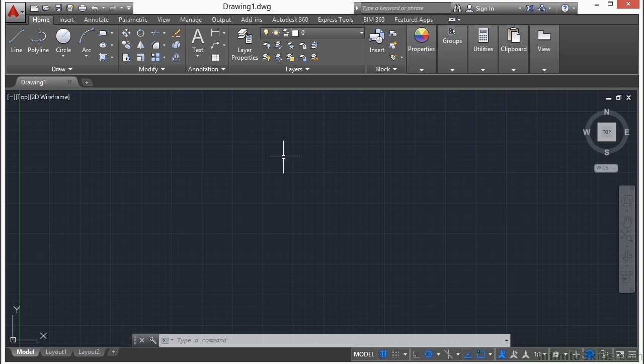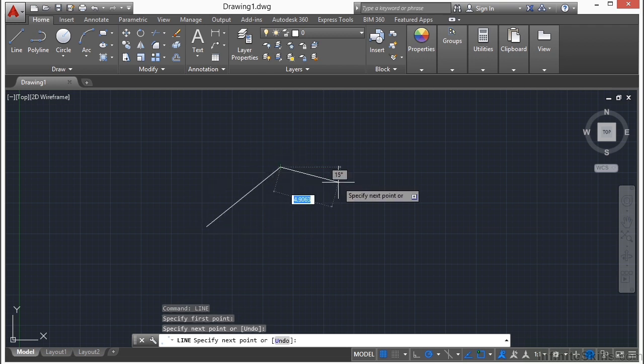Now, another way to execute commands in AutoCAD is through what's called the command line. It's found here at the bottom of the screen. That's this guy right here. You can directly input commands right into it by typing them on the command line. So you can click inside here and then start typing in a command like the line command. Press enter, and now I can draw lines.